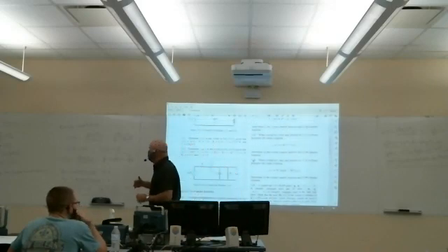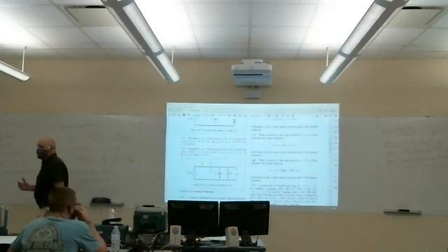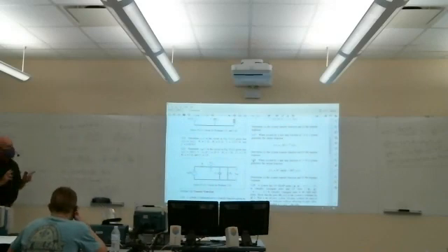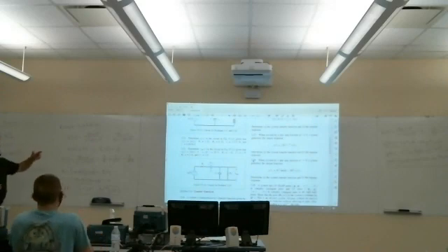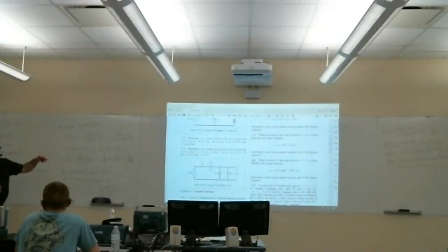So we'll see that there are actually multiple equivalent ways to completely describe the input-output relationship for any system. One is the differential equation. Another is the frequency response, which we already worked with, going right from the differential equation to the frequency response. You can go back and forth, so they're equivalent. Now we've got this transfer function, which is equivalent to the differential equation as well.